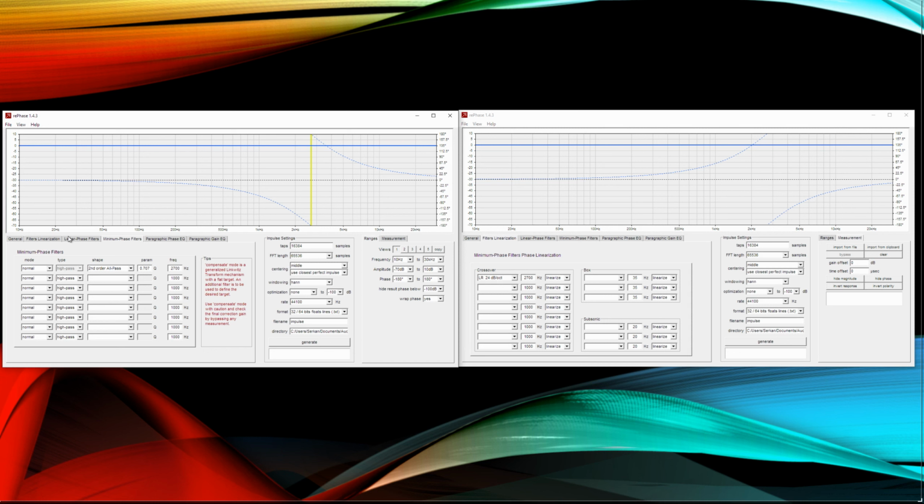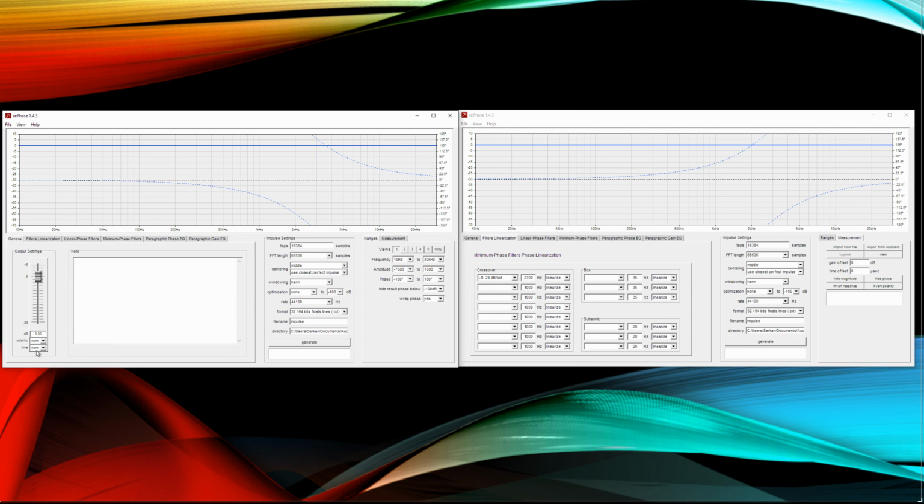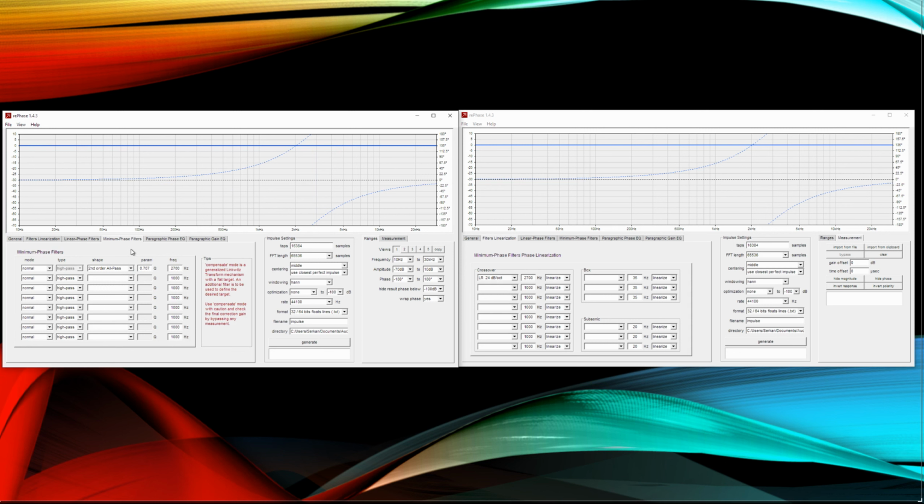But these again need to be time inverted. As you see, they are identical now. So the fourth order Linkwitz-Riley filter in my speakers' crossover can be compensated by a second order all pass with a Q parameter of 0.707, and this is also flexible.